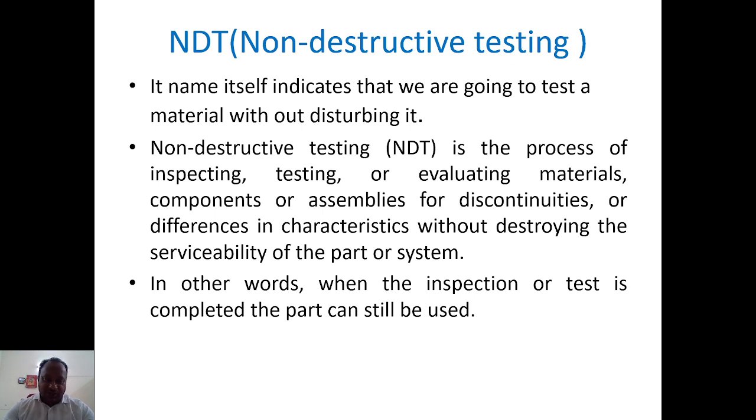Next is non-destructive testing. Already we discussed that after testing, the workpiece fails and we cannot use it for future purposes. So it is better to go for NDT, which tests the material without disturbing the process. So in this, we are testing, evaluating, and examining discontinuities. Without destroying the serviceability of the part or system, we can test the completed part, which we can then use for the process.